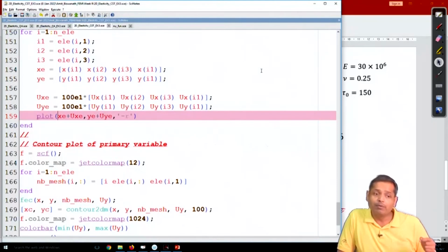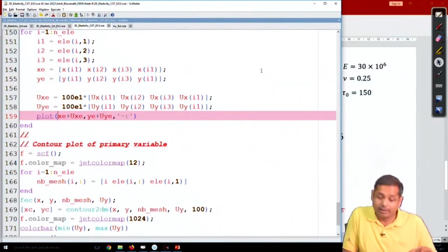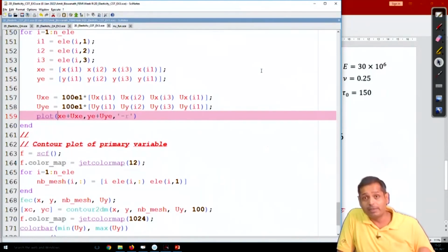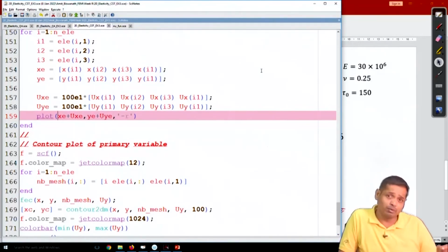Okay. Therefore, stress is generally computed at the Gauss points, at the element level. You recall that in one of the weeks when we discussed the implementation for the scalar field problem, we had to compute the flux term, and there also we computed the flux term at the Gauss points. Similarly, stress at the Gauss points will be exact. And then one thing you can do is project the stress values you have at the Gauss points to the nodal points.